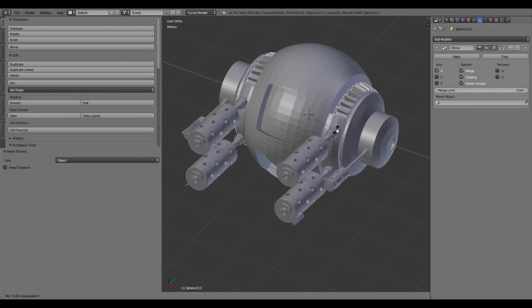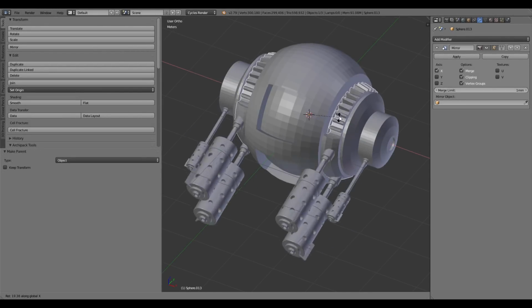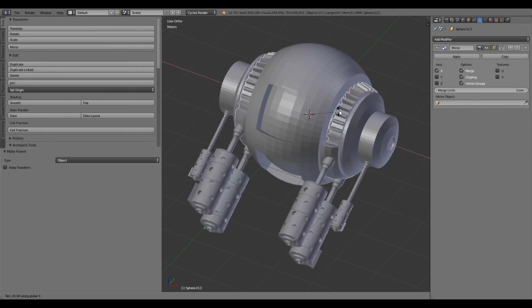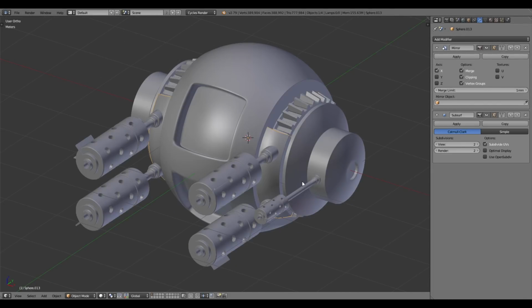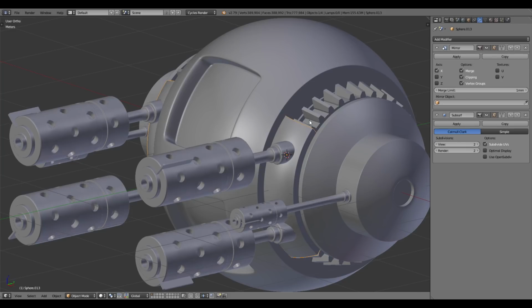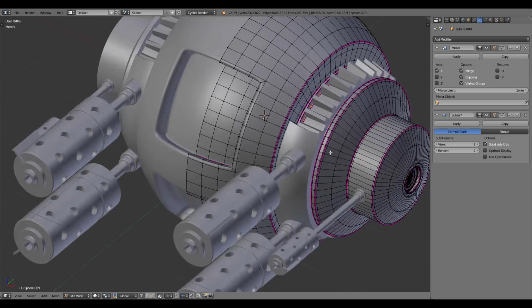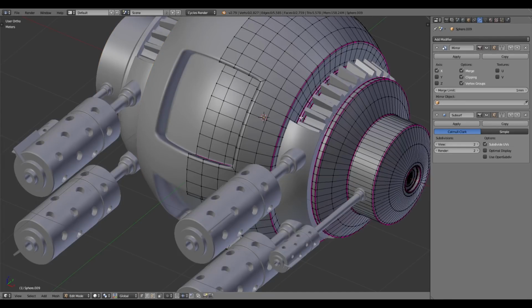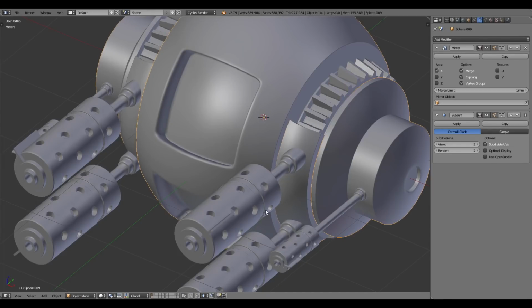Well, check it out. Now we're starting to see something that is looking really, really nice. So I've gone and just finessed up a few things, basically adding a subsurf modifier to the hull, this plate over here, and just sort of making these edges sharp in the way that we did for everything else.